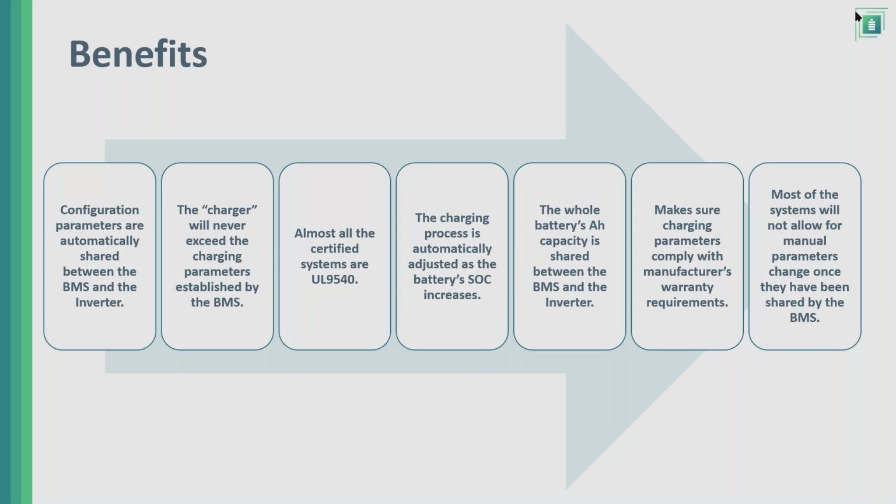But if you chose closed loop, you will not be able to change those values. You will be able to see them, you will be able to monitor them, but you will not be able to change them. You will have to change the inverter's configuration into open loop, and then you will have full access to those parameters, but you better understand what's going on and what are the parameters that have to be provided.